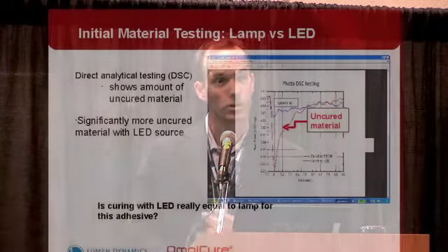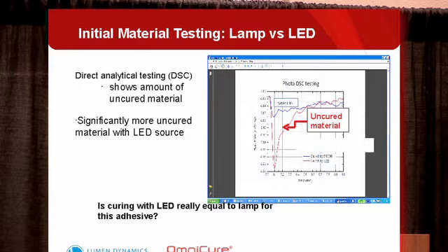Now this is just one example of one adhesive, but I think it's really important to make this distinction: curing with an LED is very different than curing with a lamp-based system. So it's very important that you follow through on the testing and the analysis, to ensure that you are getting the same cured properties with either of the technologies.